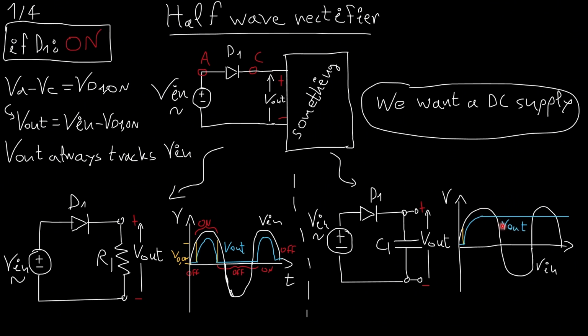This means that the output voltage is going to be a constant value, and it's going to keep being constant indefinitely. Why? Because the difference is not going to be large enough for the diode to turn on again. So the diode will be on for a little while, and then it will be off again indefinitely, forever. This seems to be a step in the good direction.